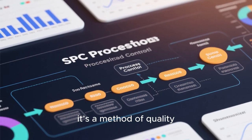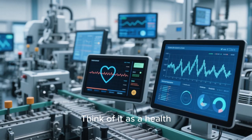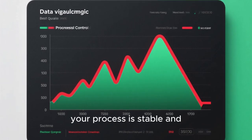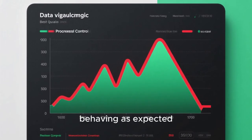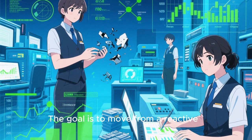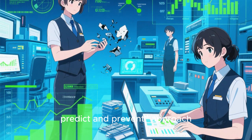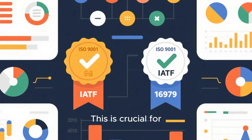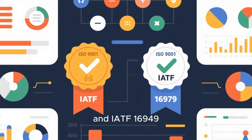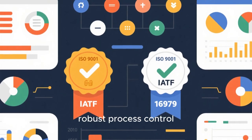It's a method of quality control that uses statistical methods to monitor and control a process. Think of it as a health monitor for your production line. It helps you see if your process is stable and behaving as expected, or if there are issues creeping in that need your attention. The goal is to move from a reactive inspect and reject mindset to a proactive predict and prevent approach. This is crucial for meeting the stringent requirements of standards like ISO 9001 and IATF 16949, which are all about robust process control.